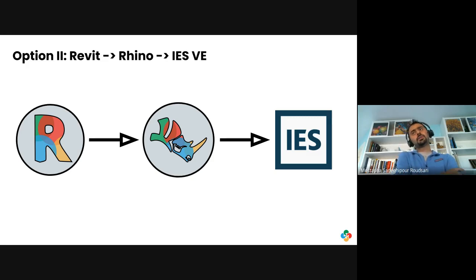Yes, if it's about doors, because we had the issue, for example, with one of these large factories: because of how it was modeled, you would get a lot of walls when it went to IESVE, and then that one you can just use PO rebuild rooms, and it just merges everything. But yes, for placing windows and doors, if you start with Revit and just select them, they should be exported to your model in IESVE.